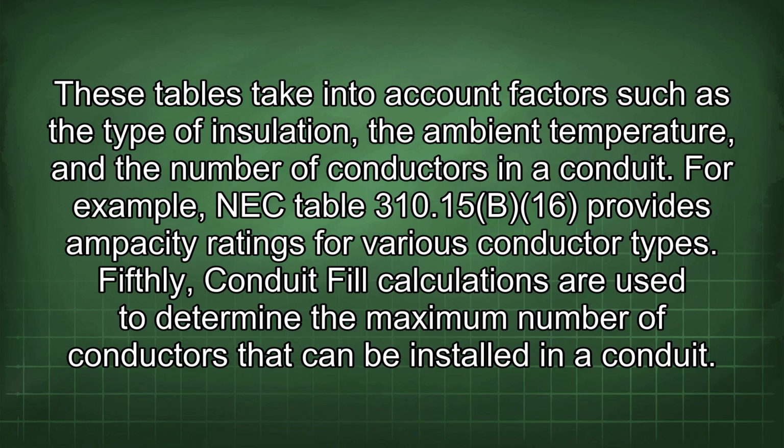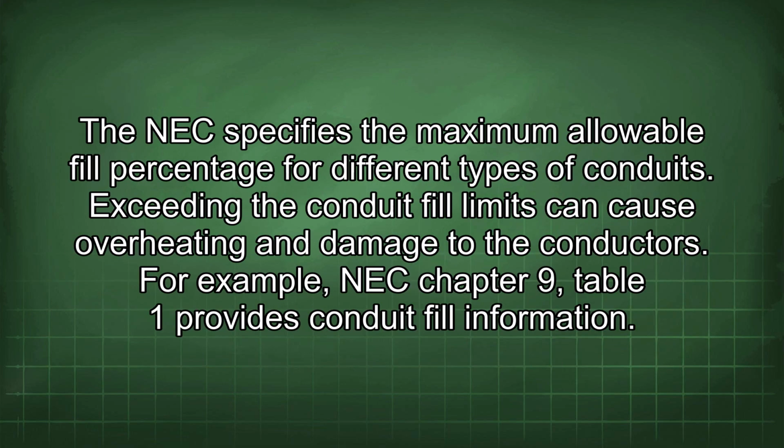Fifthly, conduit fill calculations are used to determine the maximum number of conductors that can be installed in a conduit. The NEC specifies the maximum allowable fill percentage for different types of conduits. Exceeding the conduit fill limits can cause overheating and damage to the conductors. For example, NEC Chapter 9, Table 1 provides conduit fill information.